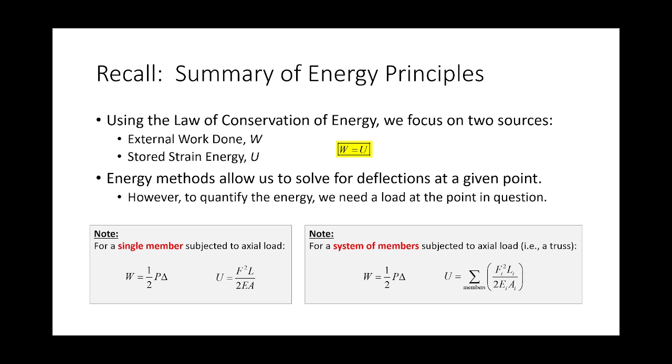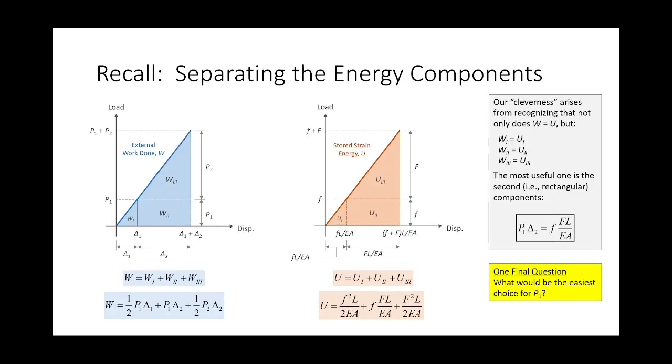So we have a deflection limit related to the day-to-day usage of the building, what we structural engineers call a service limit state. But the other reason why deflections are important is because you have to understand the relationship between forces and displacements in order to do indeterminate analysis. So it's a good thing to talk about. Now, like I said, what we did in the lecture that I posted is we looked at quantifying the energy.